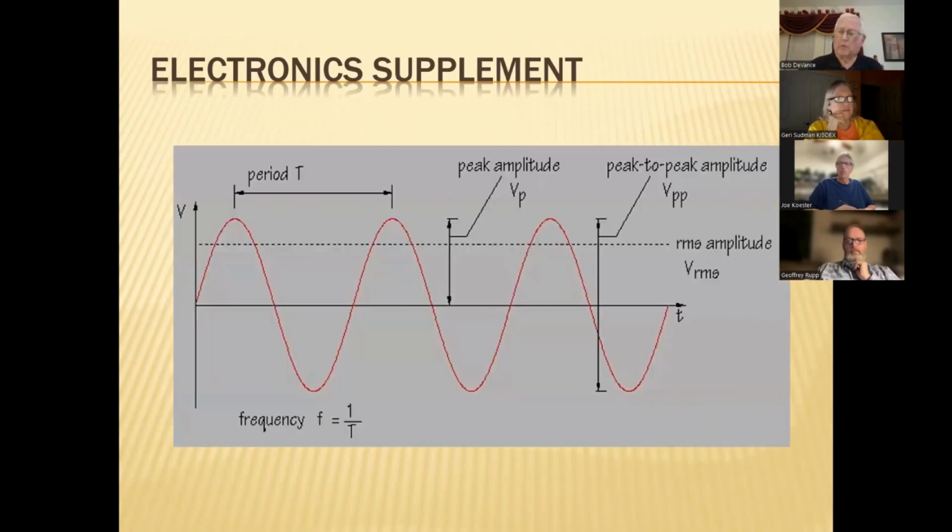Okay, the basic sine wave makes everything happen in the AC world, the alternating current world. As you can see, we start off at a given point over here. The voltage rises to a certain point, to a peak, drops back down to zero again, then descends to the negative peak and back to the starting point. That would be 1 cycle or 1 hertz.